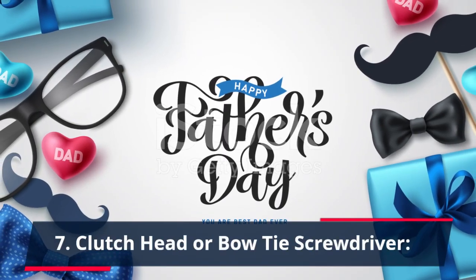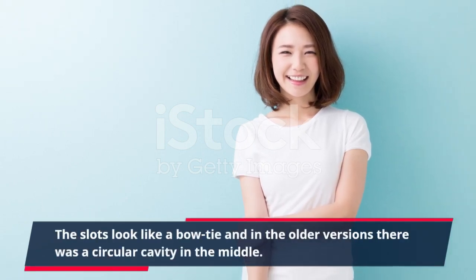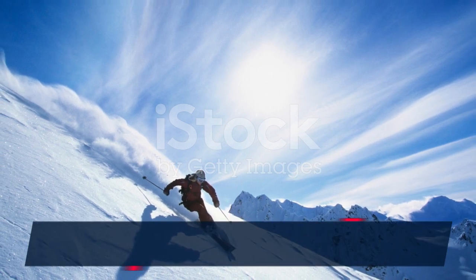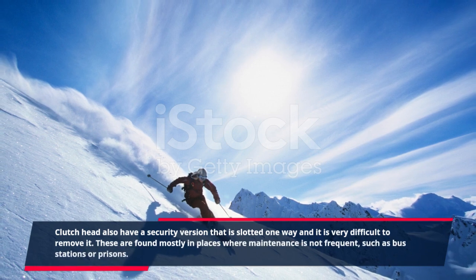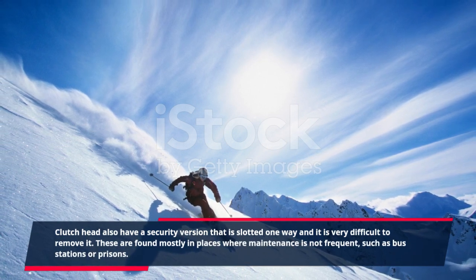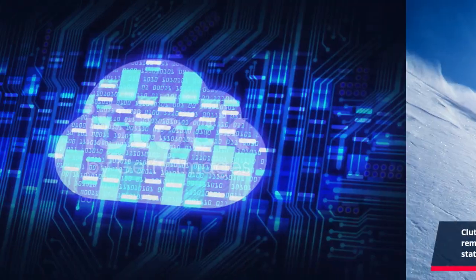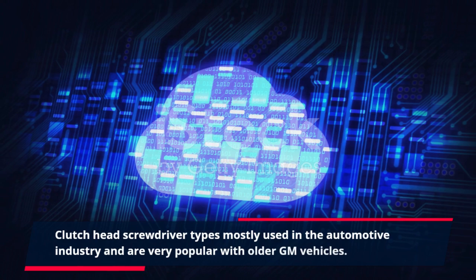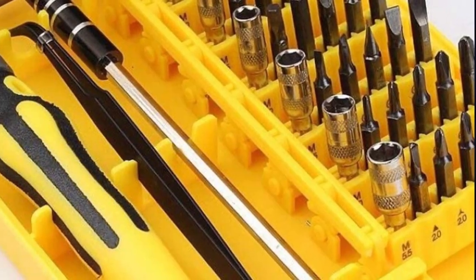7. Clutch head or bow tie screwdriver. The slots look like a bow tie, and in the older versions there was a circular cavity in the middle. Clutch head also has a security version that is slotted one way, and it is very difficult to remove. These are found mostly in places where maintenance is not frequent, such as bus stations or prisons. Clutch head screwdrivers are mostly used in the automotive industry and are very popular with older GM vehicles.